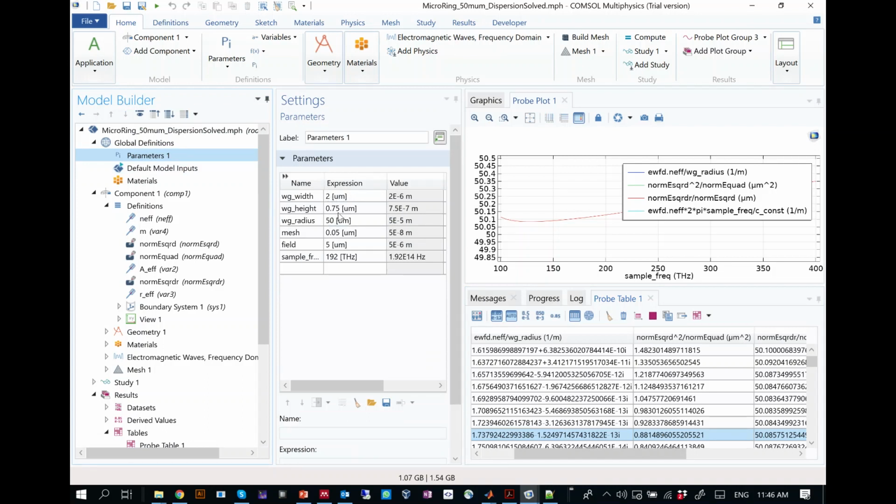And with a wider waveguide you exemplify this forcing to the sidewall, because as you make the width of this waveguide wider, at some point you're close all the way to the inner radius, and you transition your strip waveguide microring to basically a microdisc resonator. And that is only confined now to the wall because of this whispering gallery potential. And in that way, it comes all back to one another.